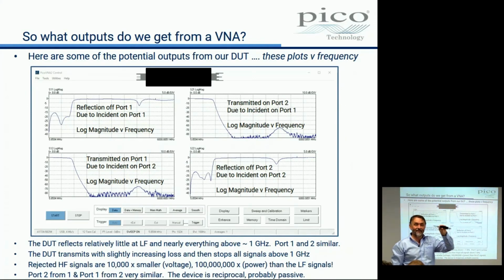What is it? It's a low pass filter. It's a low pass filter with an AC coupling. You remember the scope found that down at low frequency it was AC coupled. Yeah? So that's how I actually put a DC block capacitor. That's the 220 nanofarad capacitor that the DMM measured, right? So we do know what this thing is now.